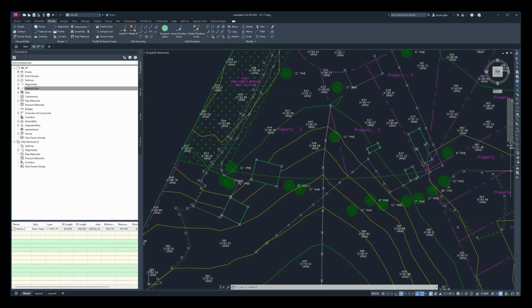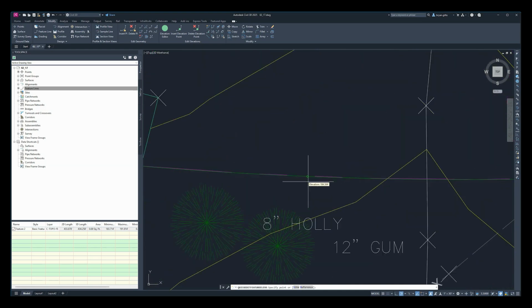All right, now we're going to go to Quick Elevation Edit and test that out. Under our Edit Elevation section, go ahead and click Quick Elevation Edit. Again, we don't have a feature selected, so we're going to need to do that. Let's move our cursor along the feature, and note the green circles that appear along those elevation points. That circle, I'll zoom in a little bit, means it's a point. If we select this, we're talking about editing the grade, and you'll see it change from positive to negative based on the direction of that triangle, which in turn refers to the direction of that slope.